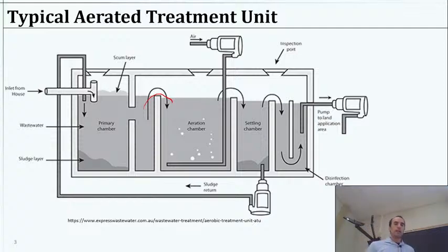So in this scheme, I think it's fairly interesting, and maybe this is for slightly larger scale things because we have these other pumps involved. I would think that this part towards the back could go anaerobic a bit, but at least right here is their disinfection chamber. So here they're disinfecting. That's going to kill off the microbes, and that'll stop your oxygen demand, because the bacteria are dying. So then you pump it out from there.